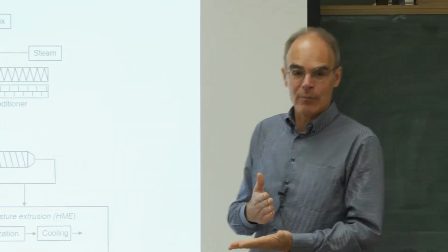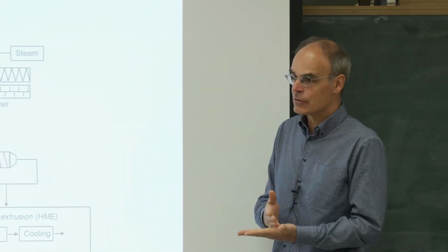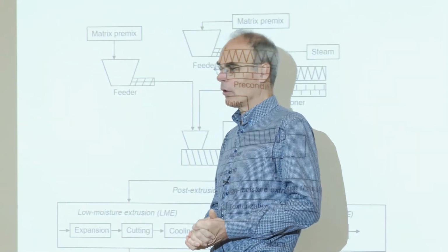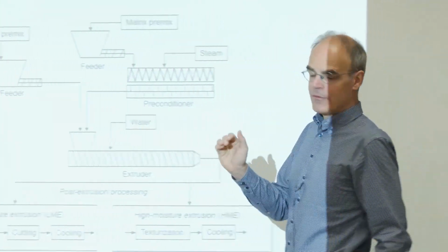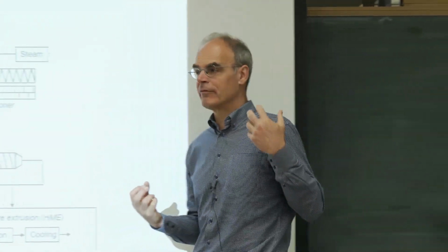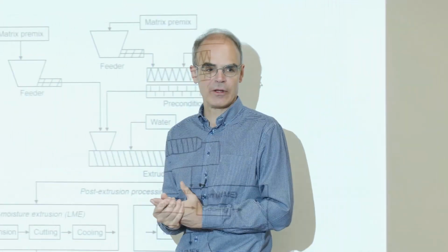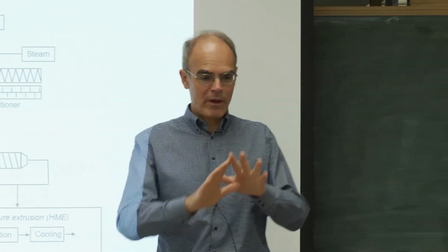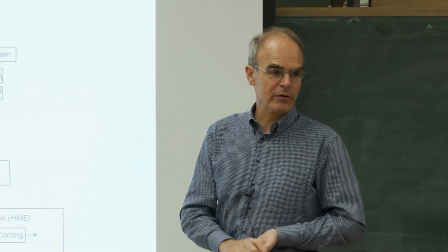But for actual practical means, in regular twin screw extrusion for plant proteins, I think 60-65% is probably going to be pretty close to the upper limit. If you are very careful and maybe have some additional hydrocolloids which bind water very effectively, maybe you could push it to 70%. But there you plateau somewhere where you can do feasible twin screw extrusion.